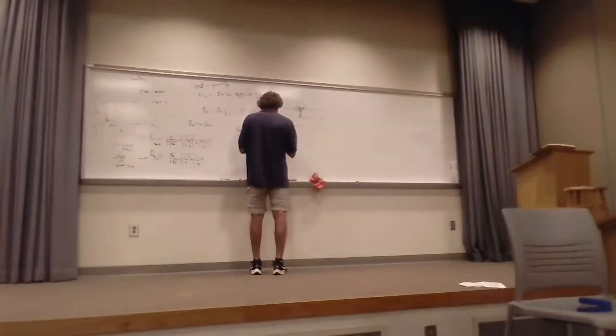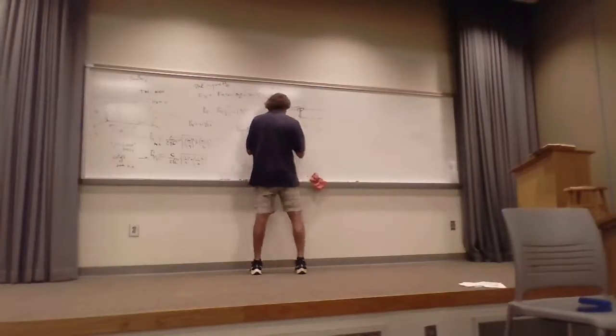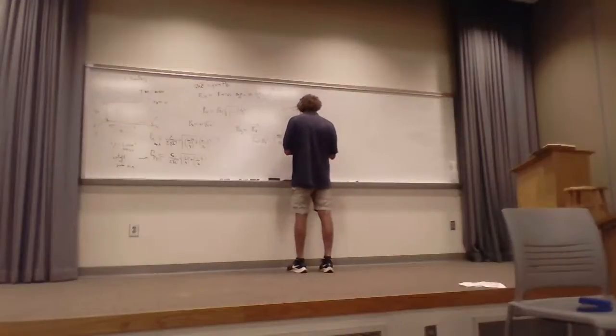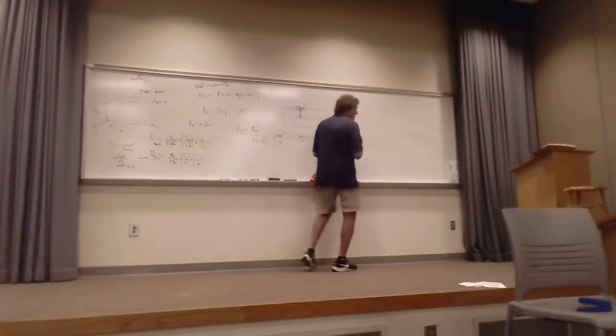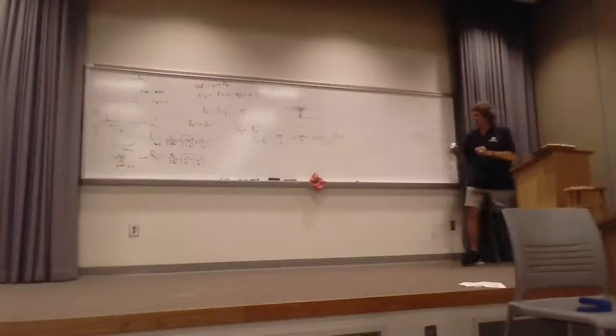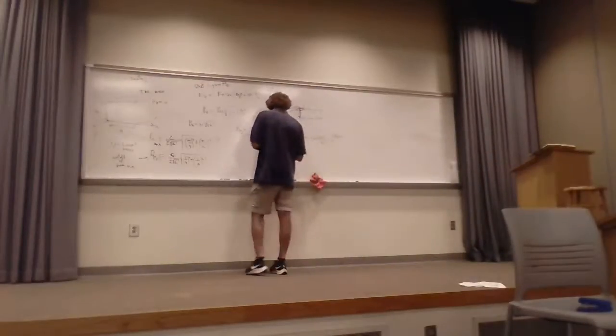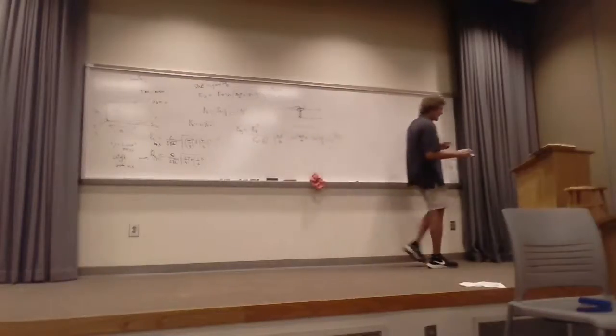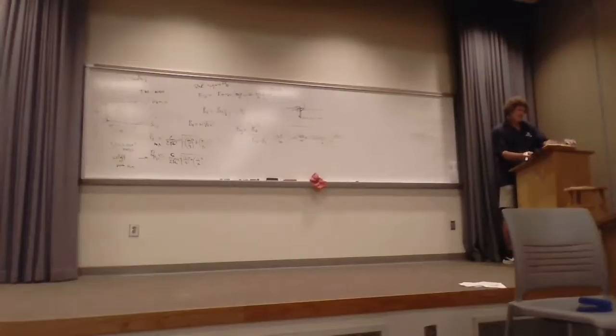and then it's going to be m pi over a, and it's going to be cosine of m pi over a times x times sine of n pi over b times y times e to the minus j beta_z times z. And in his book, if you want to know where I'm getting that, oh, sorry, this is n pi over b. This is in his book.